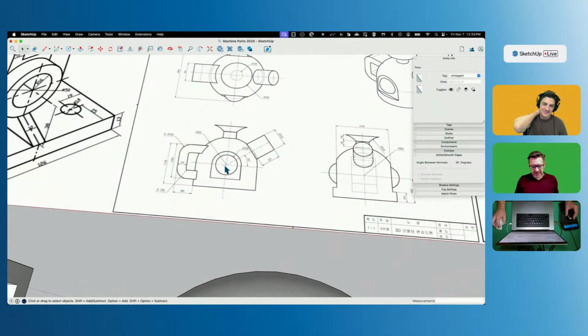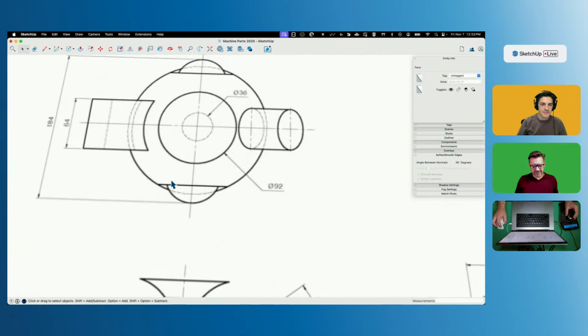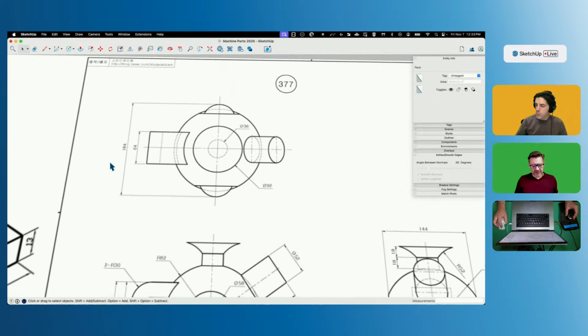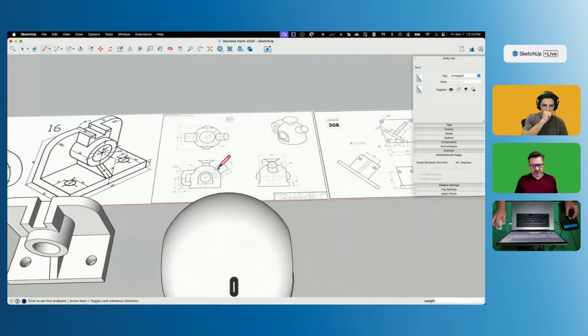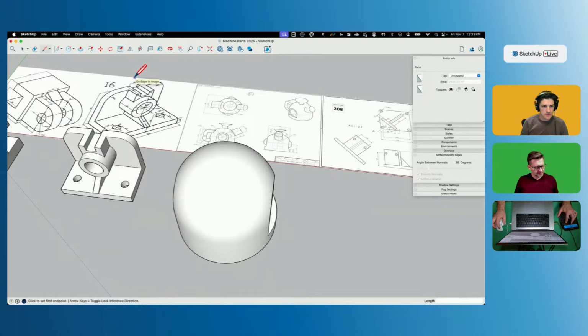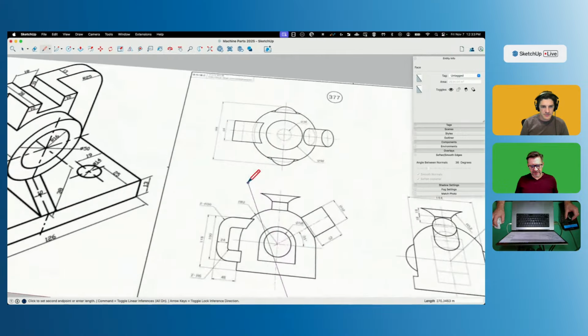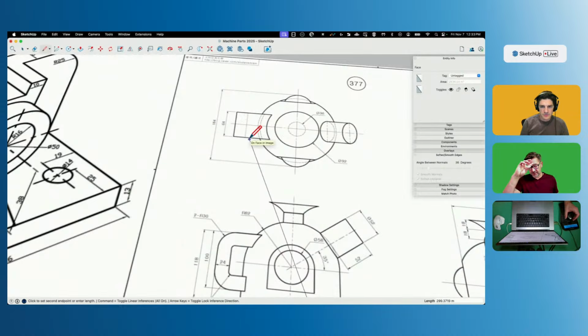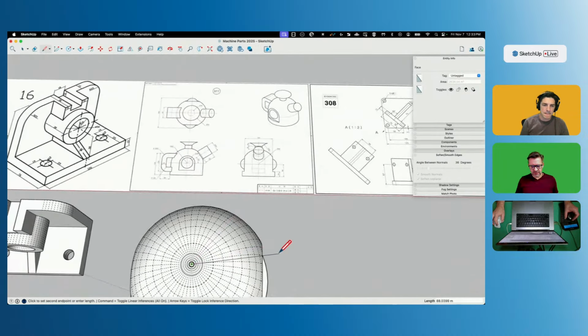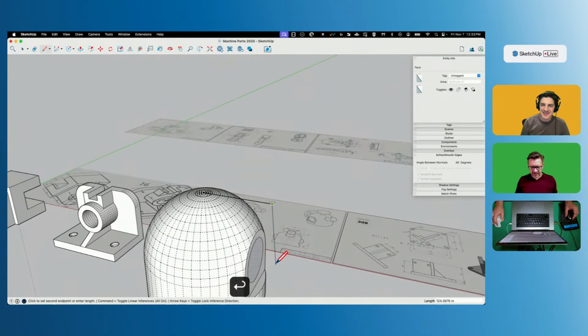Now, this right here is not actually a full half a circle. You can see that there, right? The half circle is probably somewhere back here, but it does come out a specific amount. And that specific amount is 184. So I'm going to go, again, show hidden. So I'm going to come right to this point, which I know is in the middle. I'm going to come out half of 184. So half is 92. Notice how I say things like that and move real quick before anybody can correct me?